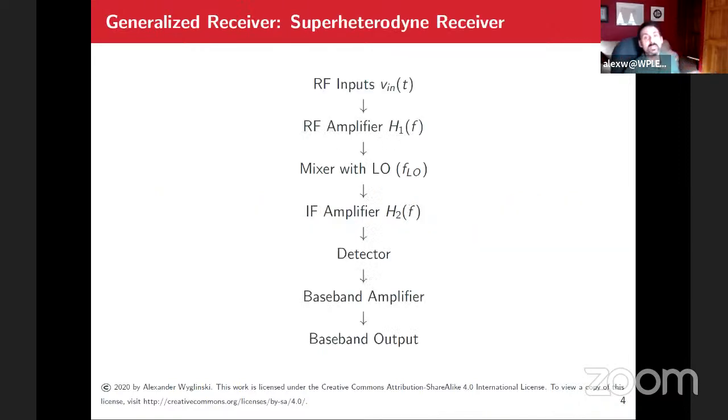So now receiver. So I mentioned this thing, the LO, the local oscillator, right? And local oscillators are actually critically important for a number of reasons, because that is what allows you to go to passband, right? It is supposed to be some sort of disciplined source of oscillation on which your carrier frequency is based off of, right? Like that fc is a frequency value. A frequency value of what? Well, it's driven by your local oscillator on your radio.